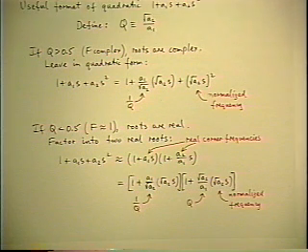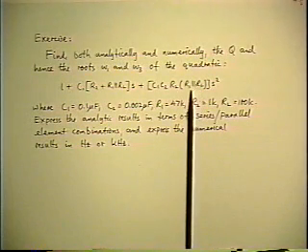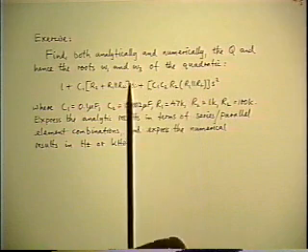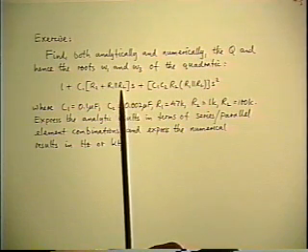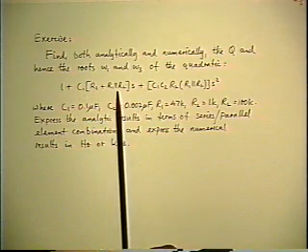That's the end of the diversion to do with properties of the quadratic. Now we go back to where it came from, which was that low-pass filter network with two capacitors that gave rise to a quadratic equation. And here it is again. This is the denominator of that voltage transfer function for the network that we already looked at, after dropping out the second part of the middle coefficient, using the numerical values to justify analytic approximations.